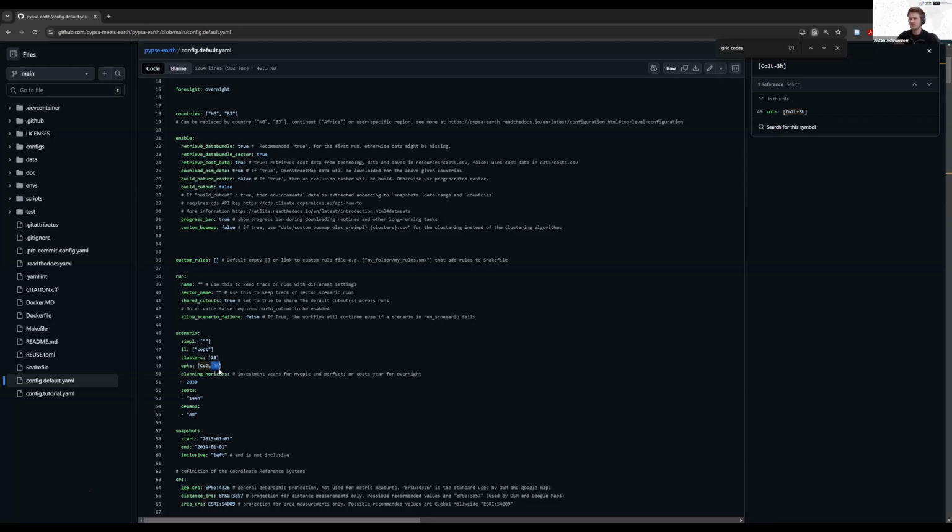You can also adjust this number. The lower you adjust this number, for example if you want a 1-hourly resolution, every hour the supply has to match the demand, and basically we are calculating every single hour of the year. So the lower the number is, the more computational effort is behind solving the model.